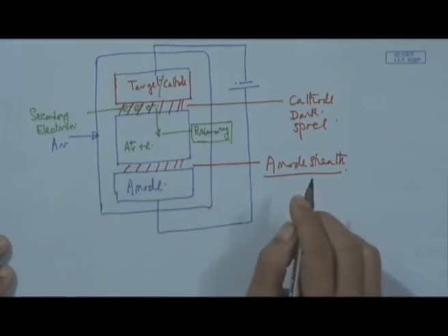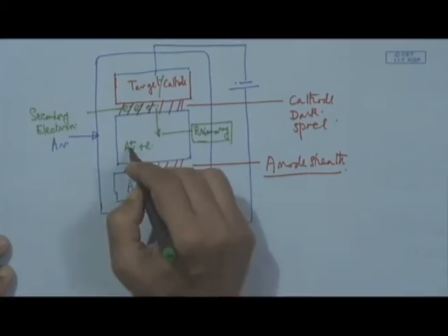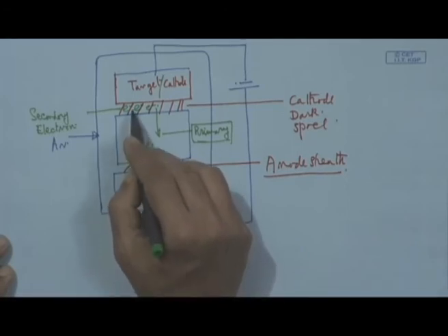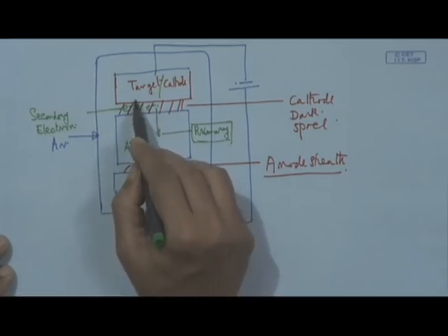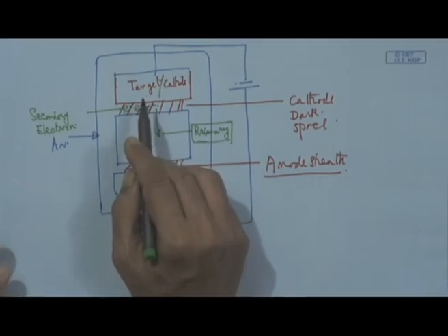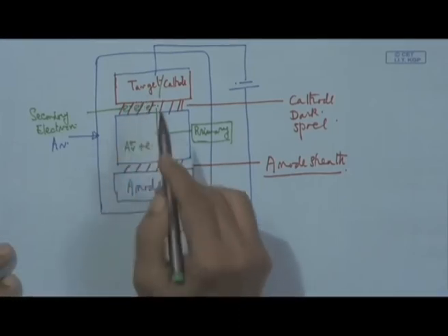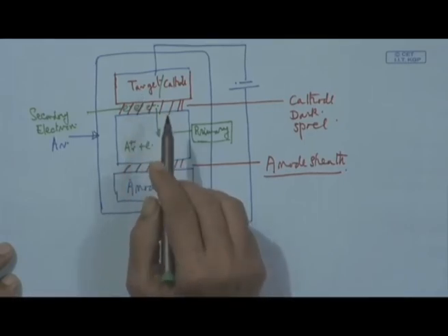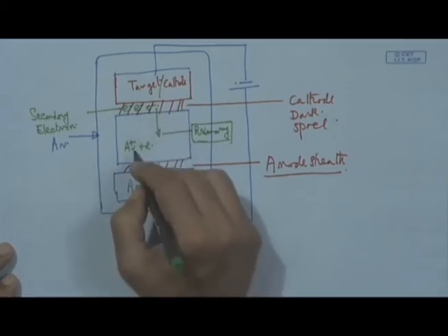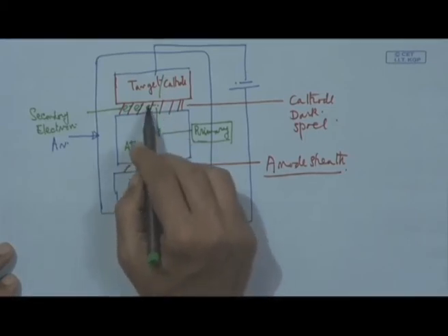With that, this argon ion will be accelerated onto this surface and strike it, causing ejection and dislodgement of the target atoms, but at the same time this argon ion can also cause emission of what we call secondary electron.